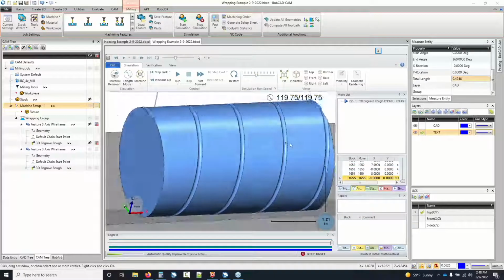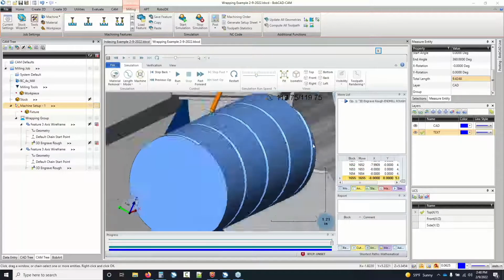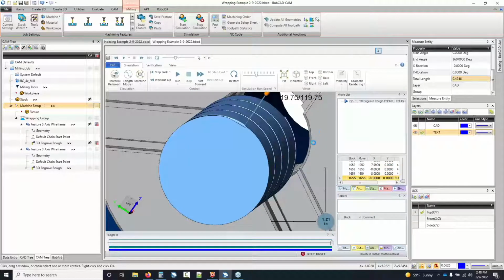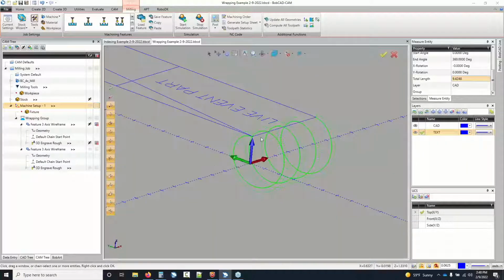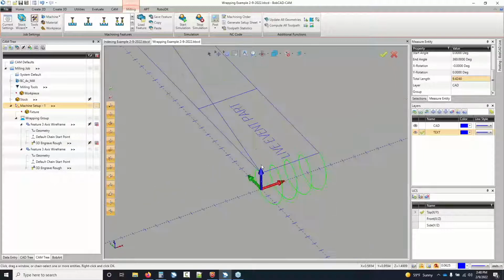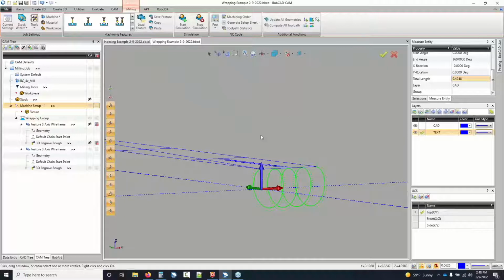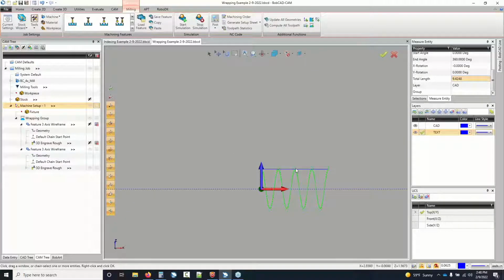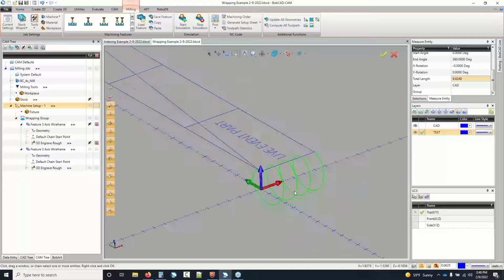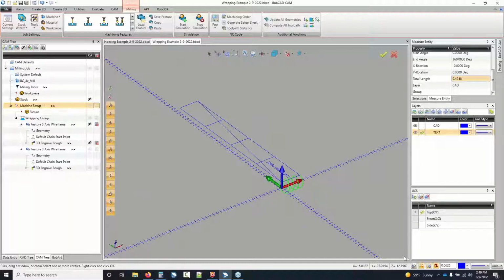And there's our little spline groove or whatever. And again, the cool thing about the way I do this, the reason I like this a lot, is I now have this rectangle that represents the width and the length of my part, and anything I put inside that box can get wrapped around the cylinder. I can put a picture in there. Just make sure that geometry is floating at the height of your part, or the radius of your part is probably the better way to say it. So there we go. Any questions?